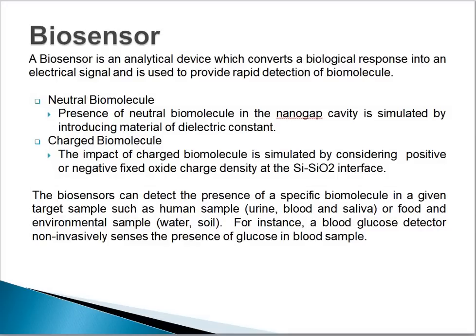In the neutral biomolecule detection, the presence of the neutral biomolecule in the nanogap cavity is simulated by introducing material of different dielectric constant. For the charged biomolecule, the impact is simulated by considering positive or negative fixed oxide charge density at the Si-SiO2 interface.